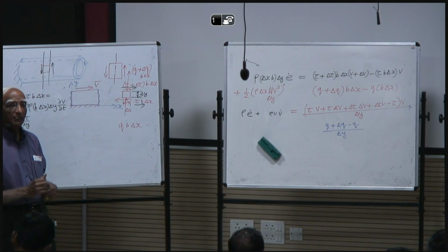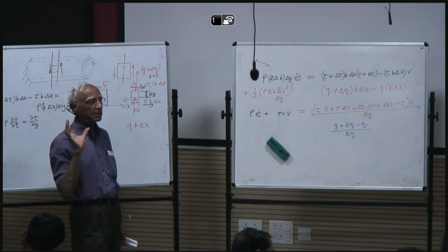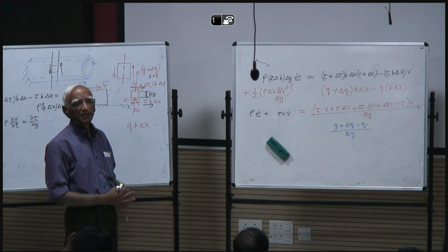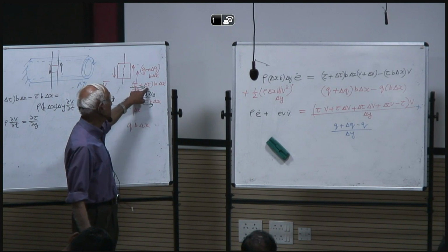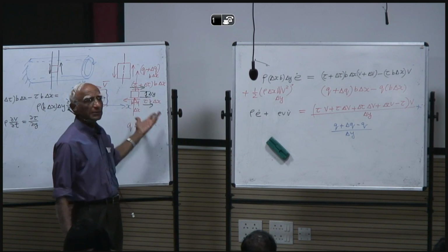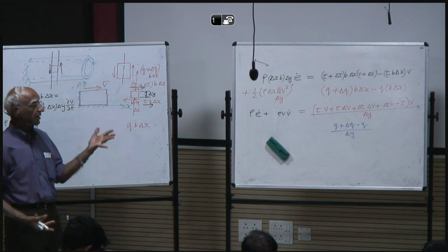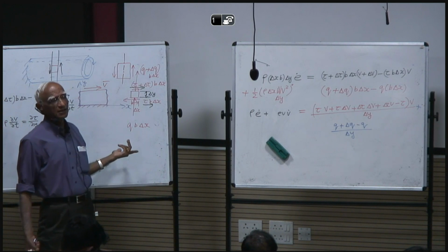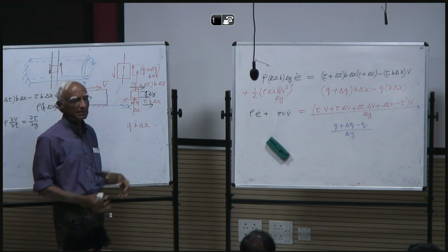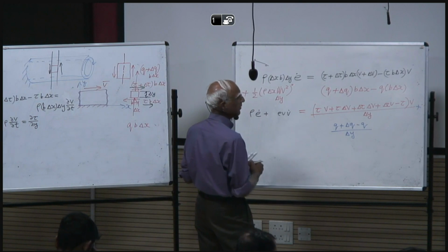So that's the rate of change of internal energy plus the rate of change of kinetic energy equals the work done by forces on this element. On this element, you have this stress and that stress. You multiply by areas, you get forces. Multiply by velocities, that gives you the rate of work done. And then you consider the heat conduction part. Okay, so let's take the limit as delta Y goes to 0.